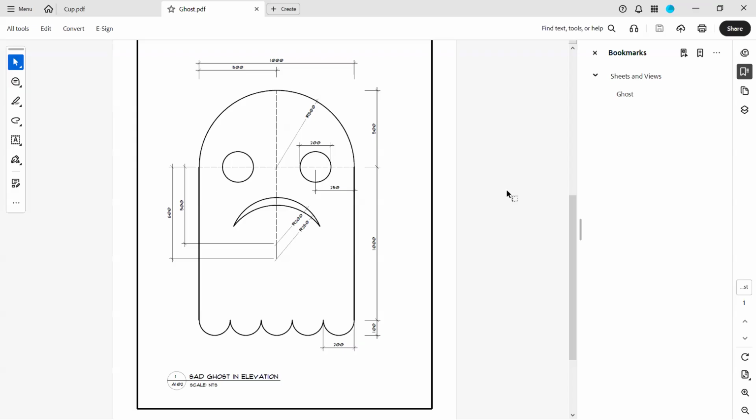One's fine. Copy? Yeah, after we call, after we drag it. Yeah, so click, select the object you want to copy, enter. It's asking you for the base point, the other endpoint. Yeah, from there you go, to there, there. The first enter, I guess. Yes.